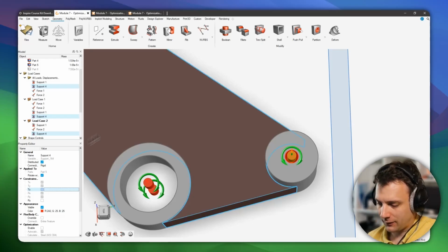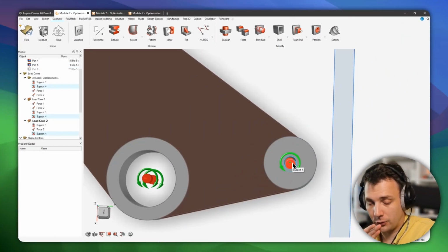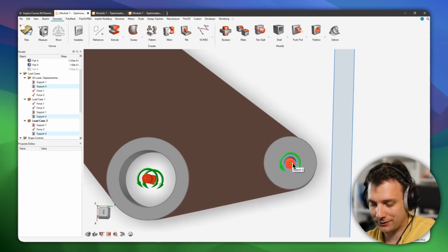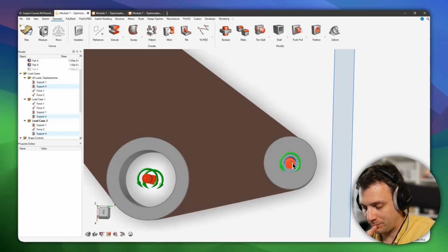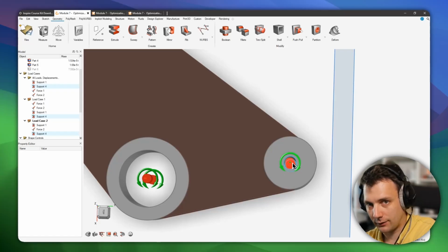I tried different things, and maybe somebody of you can come up with an even better solution, but some things did not work as I would like to. First of all, I just put a connector there and tried to constrain the master node. That did not work at all. I could not select the master node. But besides that, what's even better in circumstances like this is to model out the part which is underlying. So that means the part it connects to, the part which holds the mounting points. If those are two different parts and not structurally connected to each other, it's also a different thing.